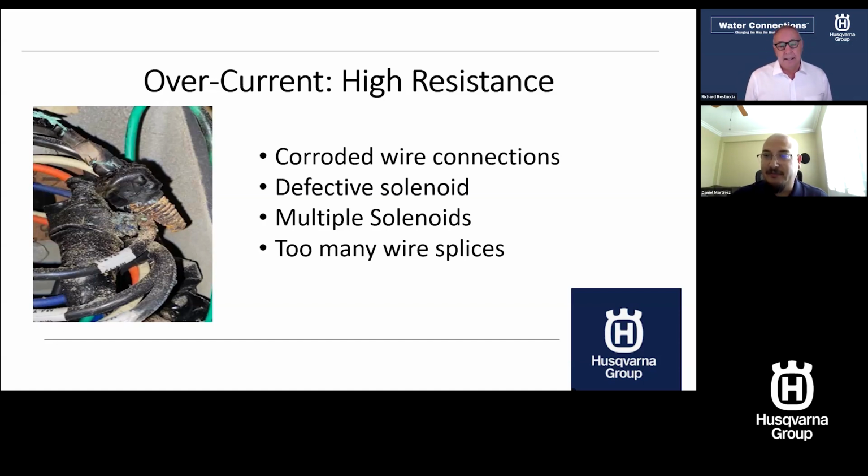In some cases, 48 zones, watering multiple times. In the last 6 months, this controller's sent an overcurrent several hundred times. So it tried to protect itself, but it keeps trying. There's nothing else it can do. It finally failed. So most of the time, they'll try to protect themselves from damage, right? The damage is to the expensive controller, not the less expensive solenoid on the valve.